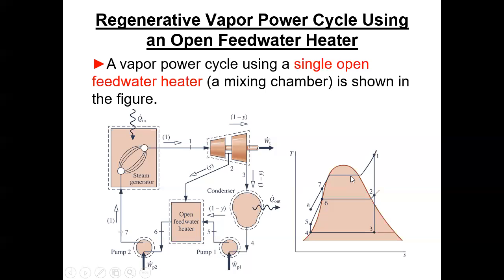Perfect, yeah. That partly answered my question, but I guess I'm just wondering, so we're condensing the steam, presumably to saturated liquid. Yeah, or maybe slightly subcooled. And then we're pumping it, and then we're putting it in the Feedwater heater. Does it go back into saturated, or is it because of the higher pressure that you're staying on the saturated liquid?